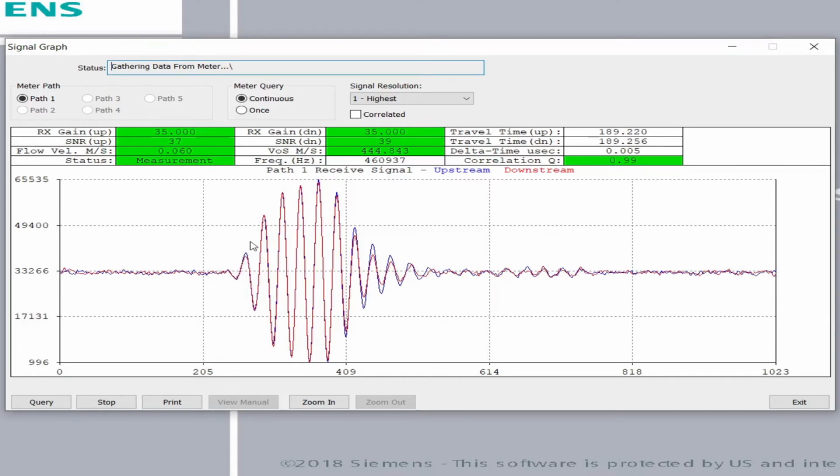In general, we like to see the received signal reach full amplitude by the 5th cycle. That indicates a good quality match to the pipe that you're installed on. And that's a textbook condition for a transducer receive signal. Once we peak, that's essentially the end of the transmission energy, because the transmission signal is only 5 pulses.